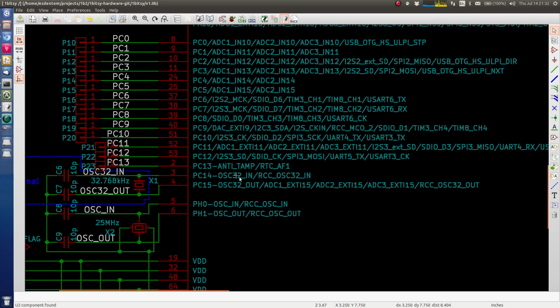So I think you put a reed switch or something in the case of your device, and even if the MCU is sleeping, using the 32 kilohertz oscillator on a battery, this pin, if it is triggered, even in low power mode, will realize that.